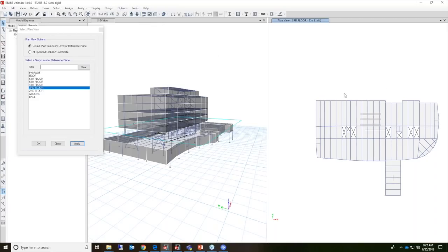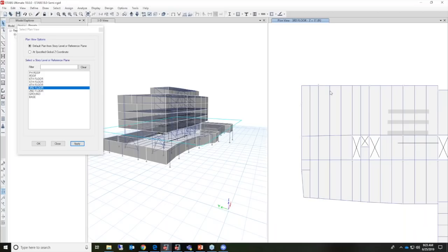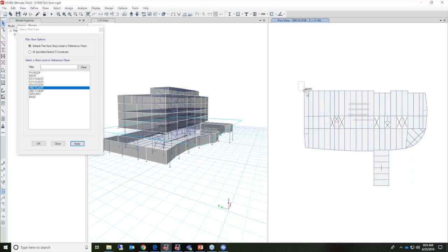And what we could do is, I'm going to take the time to select all of the perimeter beams and then use those beams as the basis of generating the cladding. So I'll just zoom in here a little bit. And I'm going to select all the beams on the extents of the structure here on the perimeter. This just takes a moment.